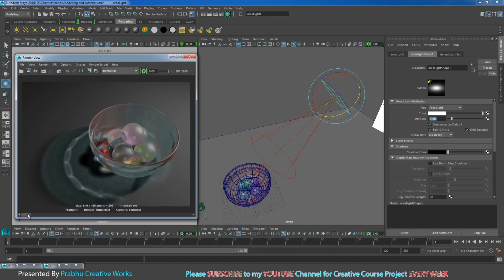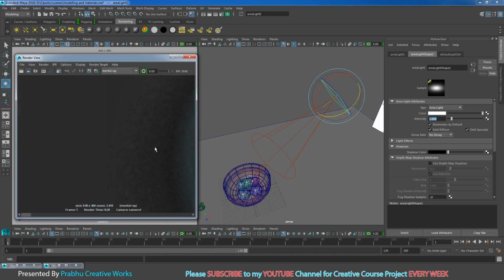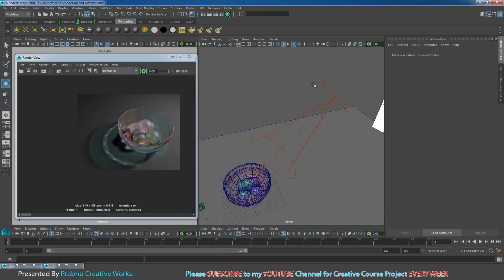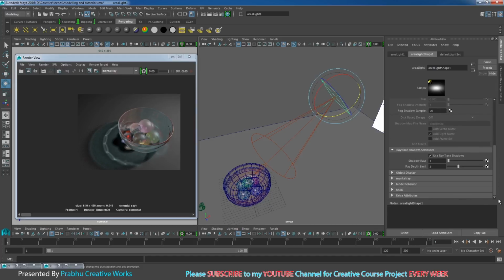So now compare the previous frame. See, our scene intensity has increased. Now I want to clear the shadow, which is splashed out here. So select the area light. Now go to Raytrace Shadow attributes. Here you need to give at least 20 shadow rays and raise the depth limit to 5.